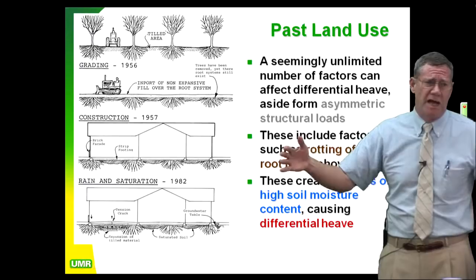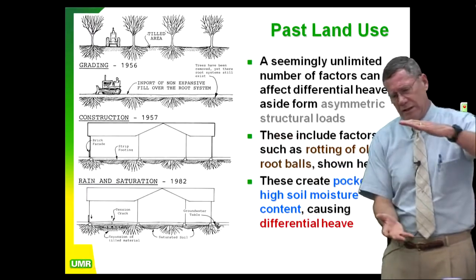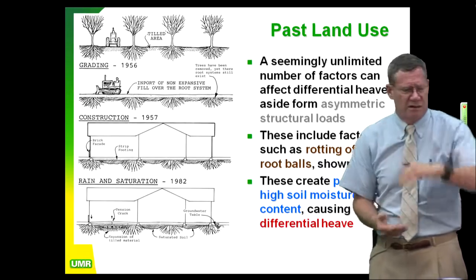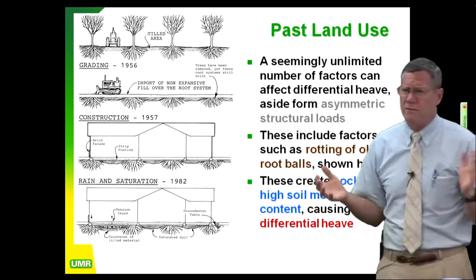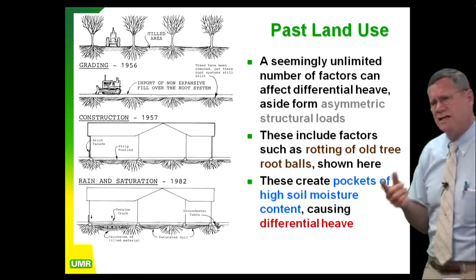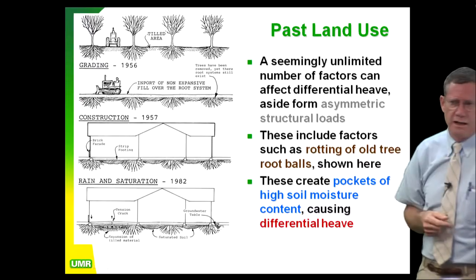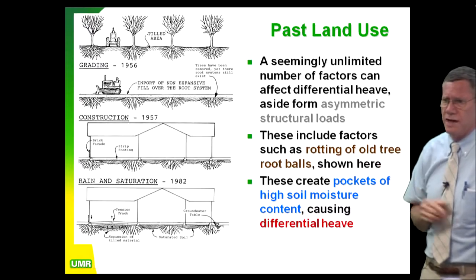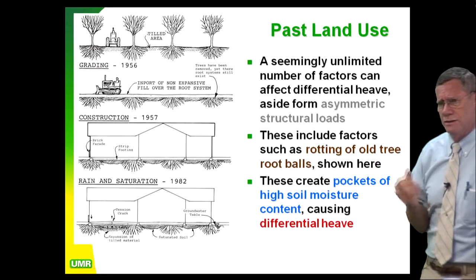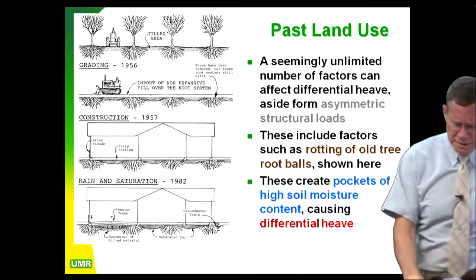So the only way you putz around on expansive soils with slab is, two ways. One, pre-pond the site for 6 weeks to 4 months, and then put in a heftier section, 14 inches, something like that. Something that's big and beefy and bomb-proof. Now, that seems like a lot of concrete. That's less concrete than the first letters from your attorney writing back. Attorneys don't do anything for less than about $2,500. They don't even blow their nose for less than that. So it increases the cost of the foundation some, but it makes it a much more resilient structure.